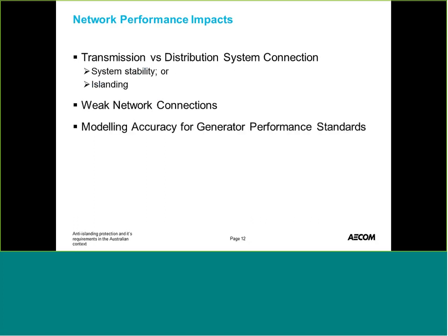Looking at weak network connections, there is a bit of a concern around stability of control systems. And when you've got an active islanding scheme, which is really controlling the output, you want to make sure that that anti-islanding scheme or algorithm is actually modeled. It's not always there when generator performance standard studies are done. So if you've got a PSSE kind of study, anti-islanding schemes aren't included in that. You really have to get something like a PSCAD model to make sure that the active anti-islanding scheme is actually modeled in there, and that there are no adverse interactions between that algorithm and the overall control system itself.